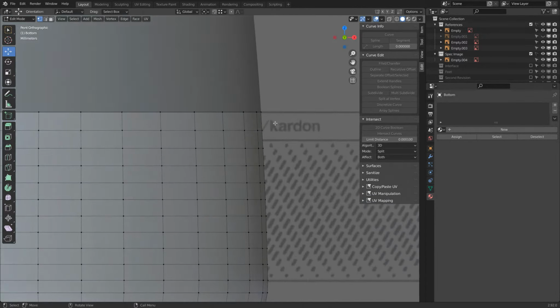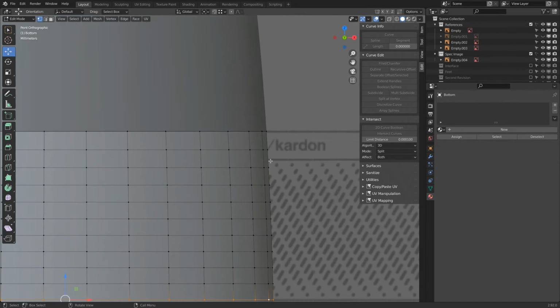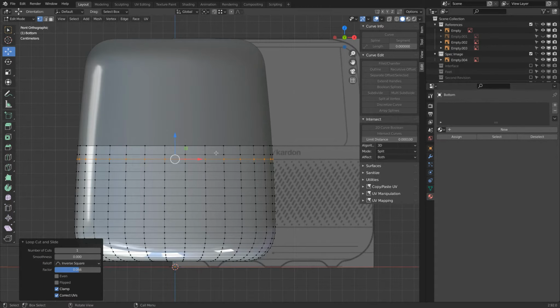Let's go into edit mode. And we see here this perfectly lines up. Here it doesn't, so Control R, click, move a little bit, and there we have now actually the correct loop cut. Because we are not going to use subdivision surface modeling here, everything is meshed fine enough to look smooth. We don't have to worry about adding geometry to distort.